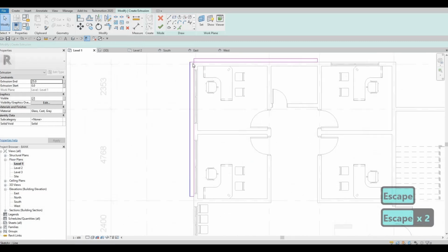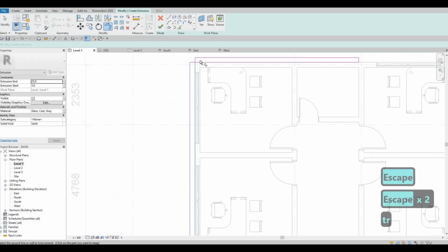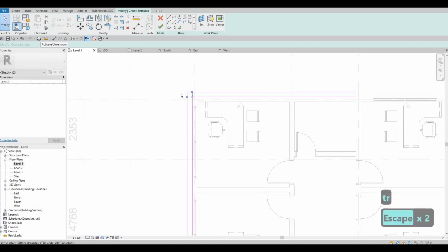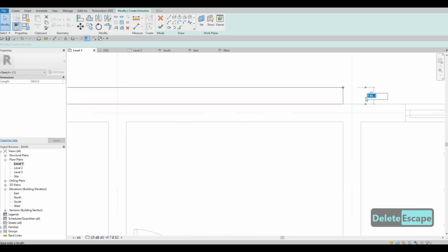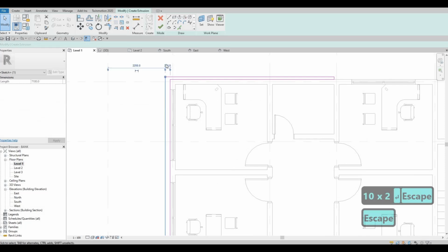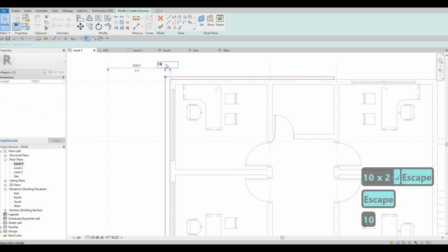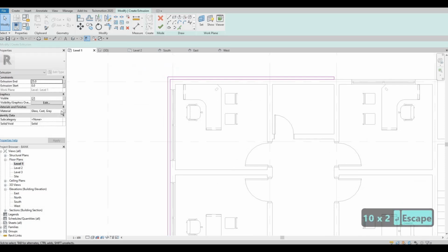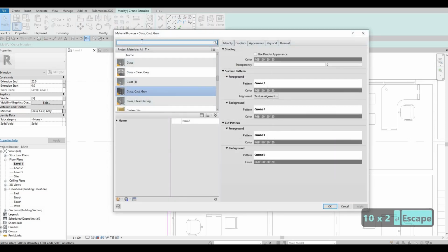And then because this is a model in place, we'll be able to change it in the spot. So here I'm planning to just put 100 thickness, and then here as well 100 thickness. In terms of material, let's do metal panel.